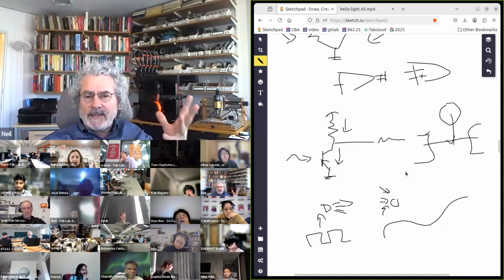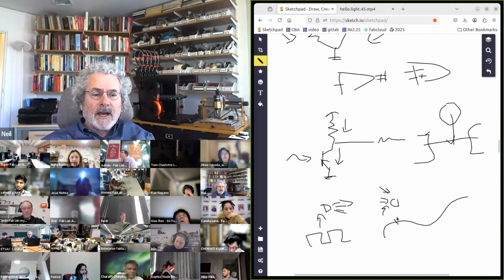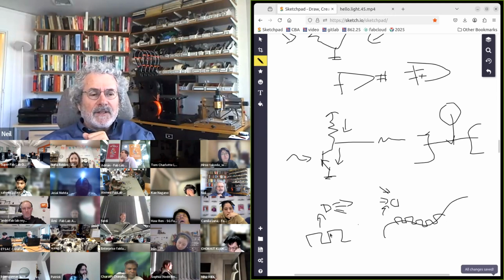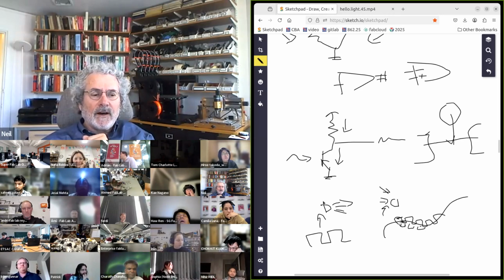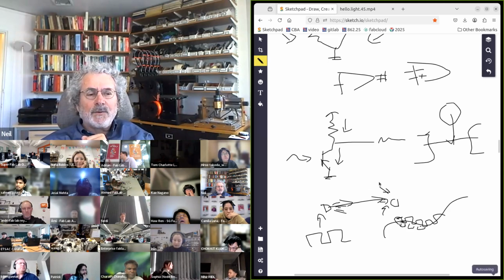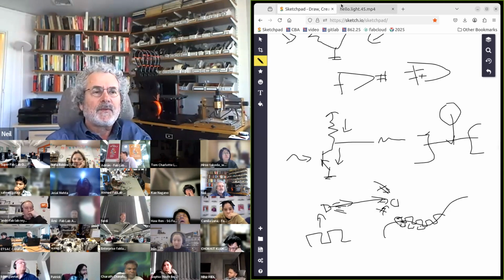It's night and day and clouds, whatever all the other light is. But on top of it is a high frequency signal, which is my modulation. And so I'm going to measure the difference between on and off. So I keep subtracting on versus off. And the difference between on and off is the light that came from here to here, and it gets rid of all of the light from all the other directions.